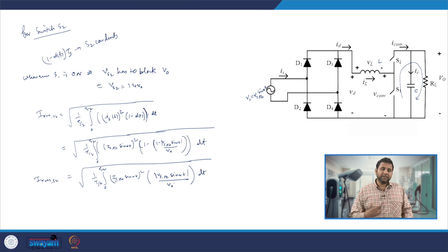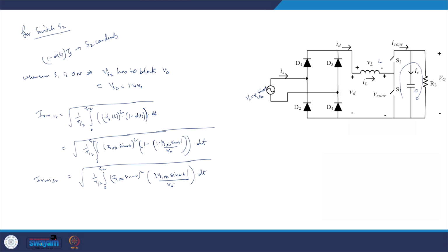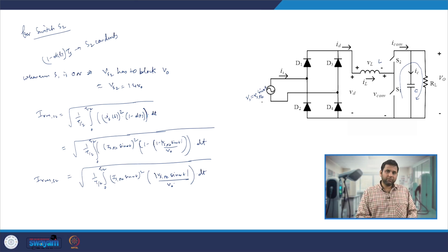Is peak you can easily calculate by recalculating the power which will be drawn from the grid, since the RMS voltage value you already know. So, you can easily calculate the Is peak as well. That is how one can easily calculate the current which will be flowing through the S2 switch.